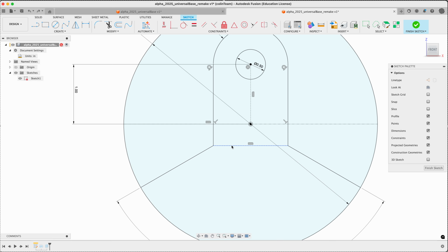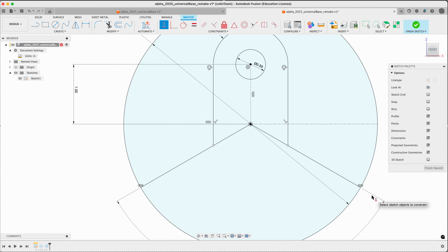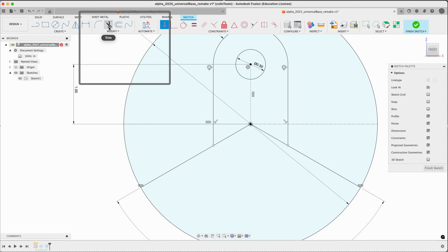One thing I can do is actually just go ahead and delete this. Right? Makes our sketch undefined. See this? If you hover, you can see this constraint. I'm just going to delete that on both sides. All of a sudden we can pull this off both ways. And because these are already constrained onto the origin, all I have to do is snap them there. We're missing a horizontality because we deleted that line, so we can just add it to the ends of the lines. Perfect.